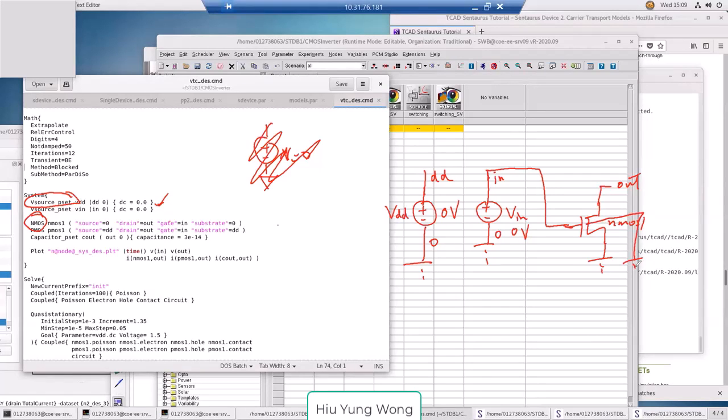Right? So here you don't have a SPICE model because you invented a new transistor. No one else in this world knows about it. You have not characterized it. You use TCAD because it solves the Poisson and continuity equations. It can predict how the transistor works. So you just use TCAD to do the simulation for this part.